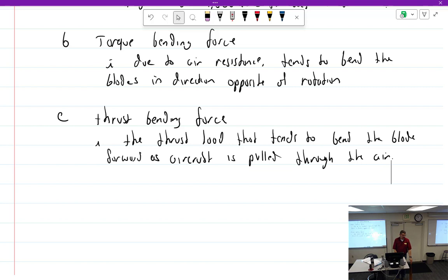But yet you can easily break them. So you want to see me get real excited? Touch my propeller. Don't touch my prop. I hate it. You will actually bend a blade and ruin it when you're pushing airplanes around. I see people doing it all the time. They'll push about right here, and they're just pushing on the airplane. Guess what that does? It bends the blade back.